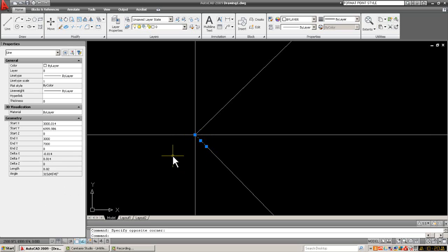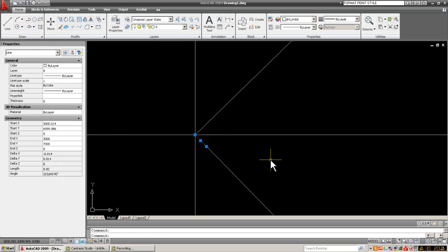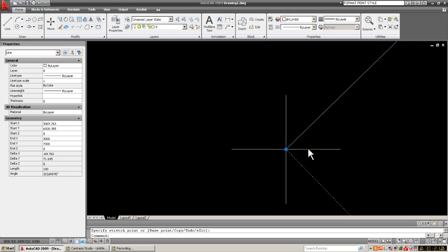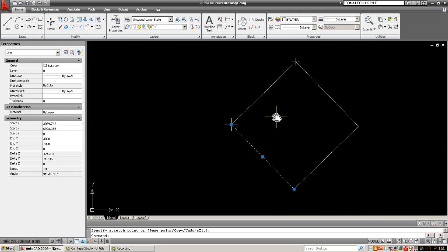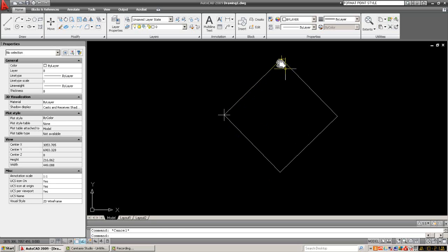Now AutoCAD can't adjust those out. We would adjust those out on the traverse sheet, and we would adjust them so that any adjustment went into the coordinates. So in AutoCAD, we can just accept that little error is there, and we just join back to the start for our traverse. If you did want to have the adjustment represented in your traverse here, what you would have to do is individually key in the coordinates of each of these points.